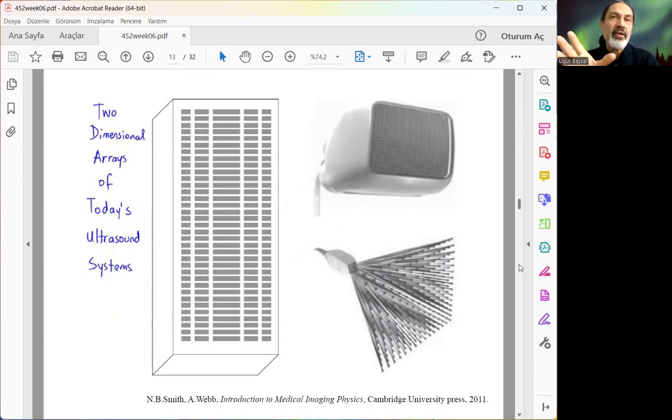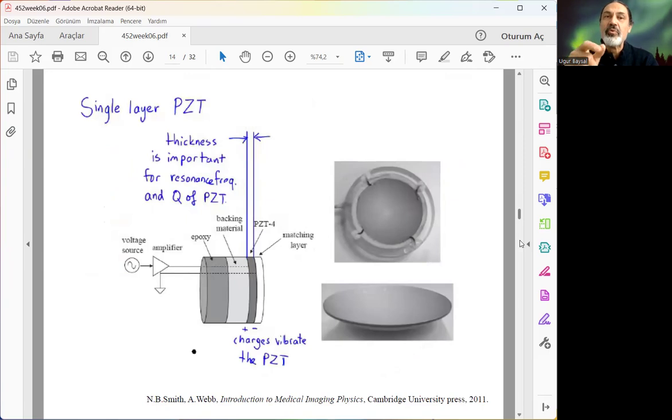So this is another type of probe. You can arrange the alignment or the focusing of ultrasonic waves in multi-channel piezoelectric crystals. Here, each little element of the two-dimensional array represents one piezoelectric crystal, and its size may differ according to the sensitivity or energy distribution pattern of the selected probe. So that's another type of design criteria.